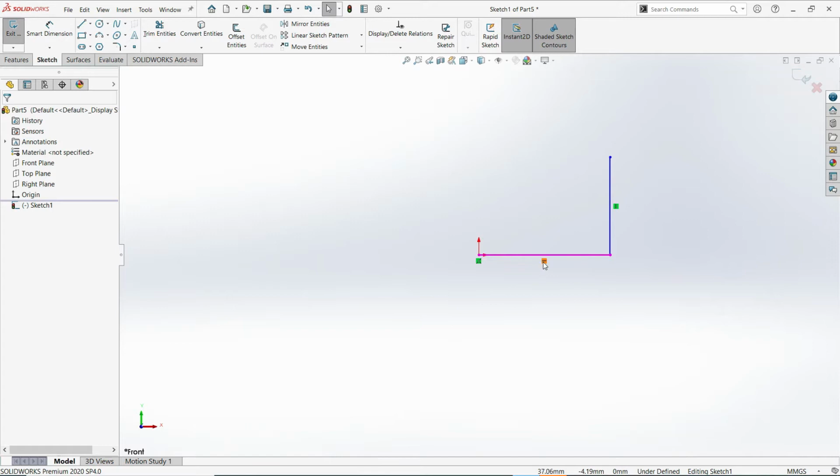If those added relationships are not visible, you may want to view them using the hide or show items and select view sketch relations. If this is not selected, no sketch relations are visible in your sketch entities. So I'll just leave it that way. So these geometric relationships can be between two objects such as parallel, horizontal, vertical, or even perpendicular.